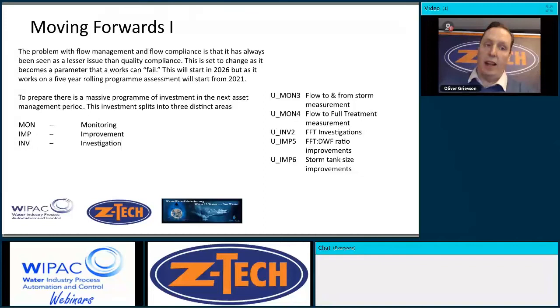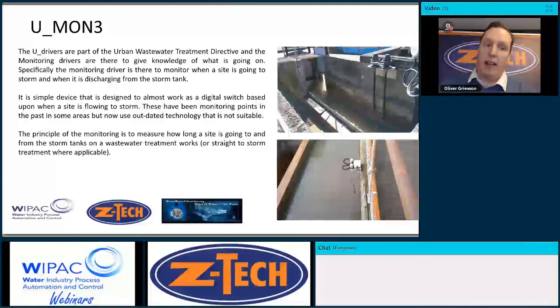The ironic thing about that is a metre or two downstream of that penstock, there's a perfectly good working flume, which is an absolutely perfect control device. And yes, you may need a bit of change in the height of the storm weir to make sure you control properly. But guess what? It can be a great thing.